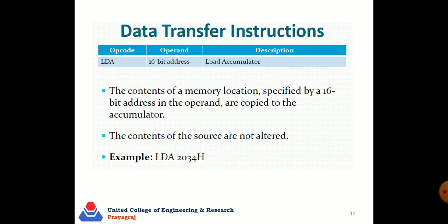Next instruction: LDA 16-bit address. LDA means load the data in the accumulator from a given 16-bit address. So the content of the memory location specified by the 16-bit address in the operand is copied to the accumulator.